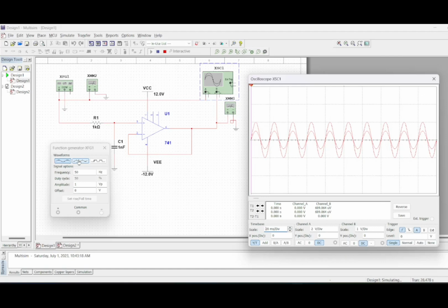By examining the output waveform, we can make some observations. At 50 Hz, since our input signal frequency matches the desired low frequency range, a well-designed low-pass filter should allow this frequency to pass through with minimal attenuation. Therefore, the output waveform should closely resemble the input waveform with an amplitude close to 1. This indicates that the low-pass filter is successfully passing the low frequency component.